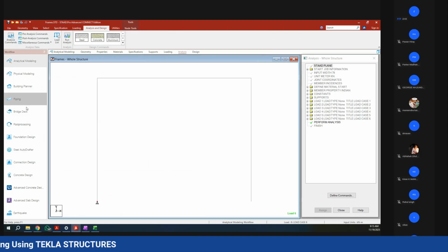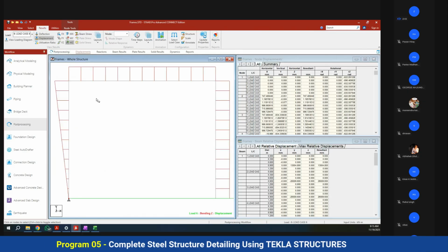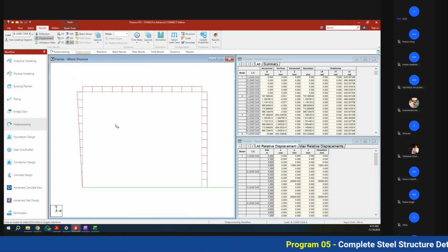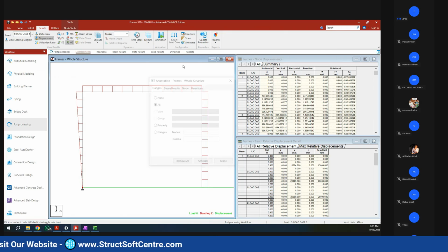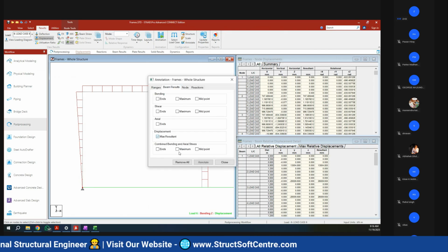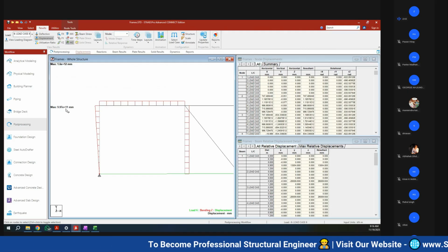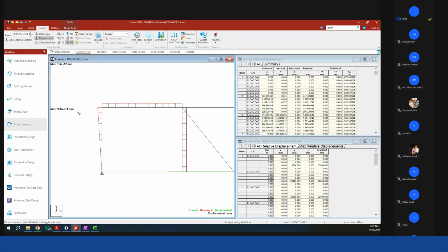Let's see the warning. Or first, let's see what kind of moment I'm getting. Here it is zero. And see, practically deflection is infinite, because you see the model has already fallen down. If I want to measure the value of deflection, let's see. You are getting some big value, 9.97 × 10^11 mm. Yes, so this is practically not possible. Something is wrong.